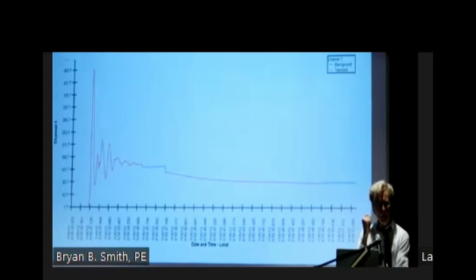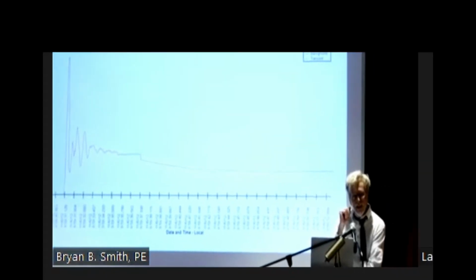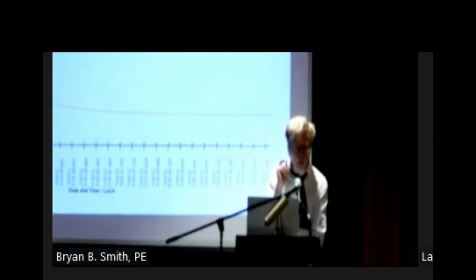What's going to happen when you start up this pump is all your safety relief valves are going to go off. And guess which way they're pointing? They're not pointing down. They're not routed. You're going to kill someone because they will open up.